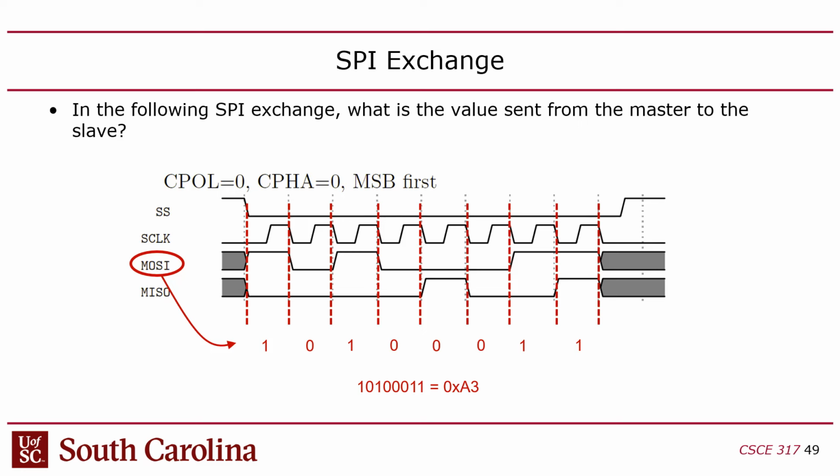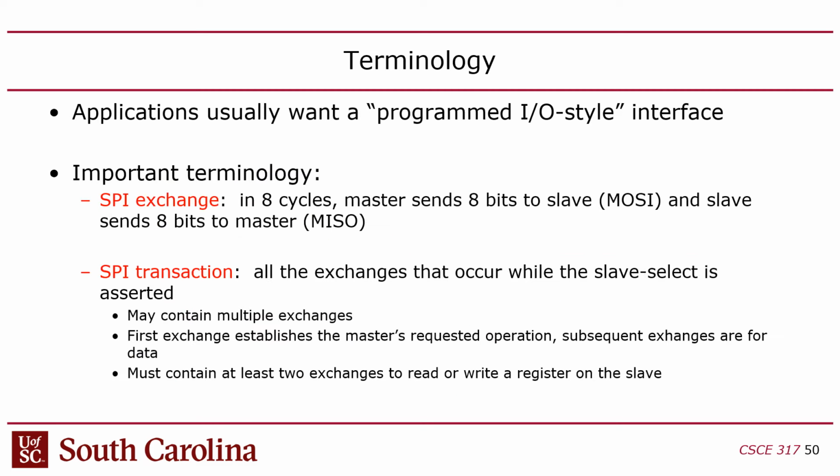I don't think SPI defines that. So you could have a situation where you have a peripheral expecting least significant bit first, although I think in most cases it's MSB first. In any case, you just go to the datasheet and it should be all there. But it's an option, and it almost comprises another set of timing modes. Like you've got to know CPOL, CPHA, and whether it's MSB or LSB first. But I think in most cases it's MSB first. But you should confirm that.